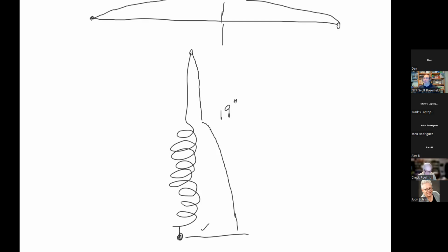Well, what happens to all the wire that's all coiled up if I have current that's going this way and current that's going this way right next to each other? They tend to cancel each other out. So this really means that this antenna essentially is very, very non-functional down in that region. It does not do a very good job.